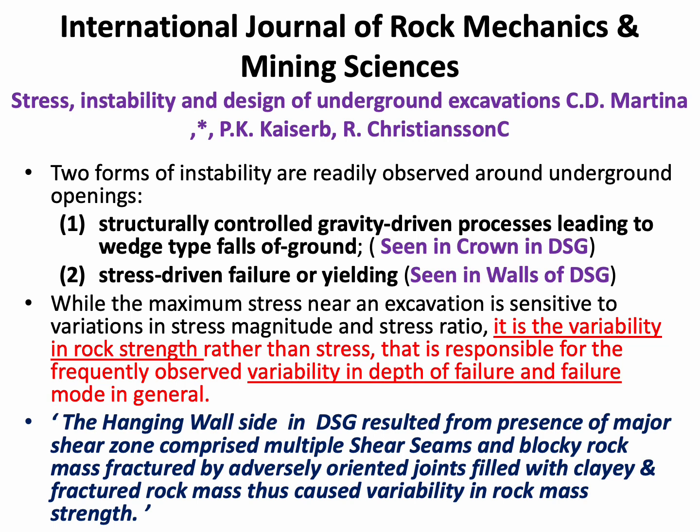While the maximum stress near an excavation is sensitive to variation in stress magnitude and stress ratio, it is the variability in the rock strength rather than stress that is responsible for frequently observed variability in depth of failure and failure mode in general. So it is variability in rock strength which is causing variability in depth of failure.